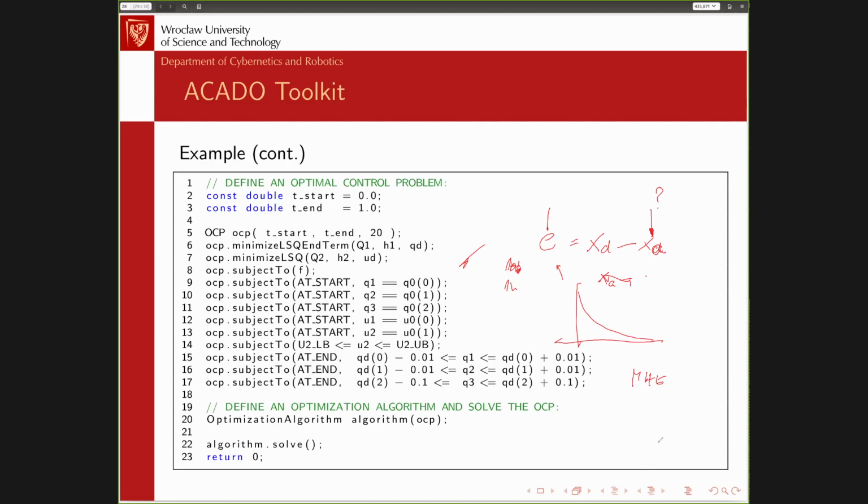In predictive control, you look into the future to find the optimal solution. In moving horizon estimation, you are here, you measure something here, and you want to know how you achieved this. You look into the past, so you try to fit your model best to the data you collected so far. And you can use moving horizon estimation for estimating the state, but also unknown parameters of the system, because you can look for the parameters which best describe the measurements you have.